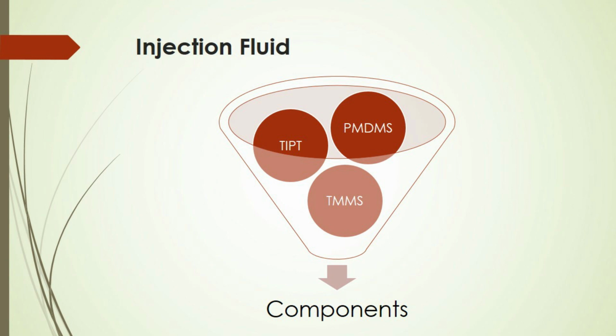For these silane-based fluids, silane activity, chain length, rate of rejuvenation, and penetrability are all very important properties. While the aforementioned first-generation rejuvenation fluid was successful in prolonging the life of electrical cables, the difficulties of injecting the fluid into cables and the delayed reaction rate caused the fluid to be distributed in an inhomogeneous manner. A newer rejuvenation fluid mixture consisting of PMDMS, TIPT, and our third component, the TMMS, was designed to speed up the rejuvenation process response pace.